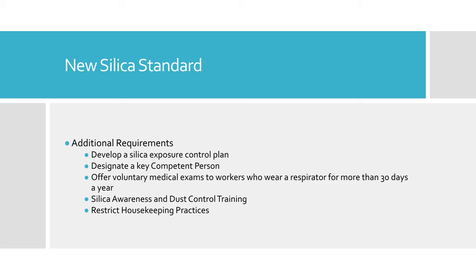Housekeeping practices must be used to prevent additional dust exposure. The use of dry sweeping or sweeping with compressed air is now prohibited. To clean, you must use a HEPA vacuum, wet sweeping, or an approved sweeping compound with a dust respirator.